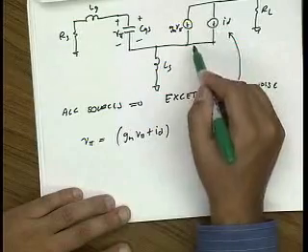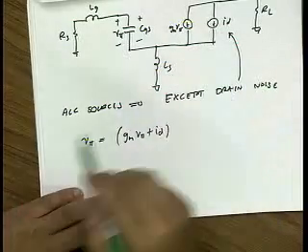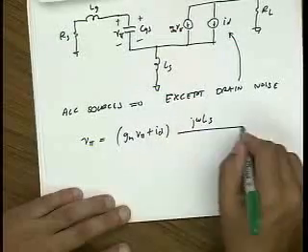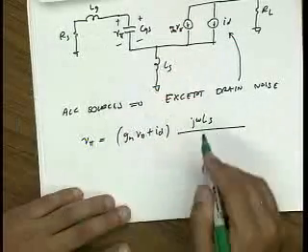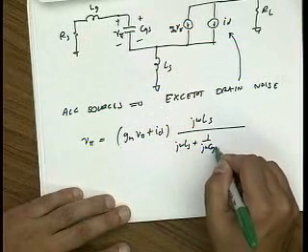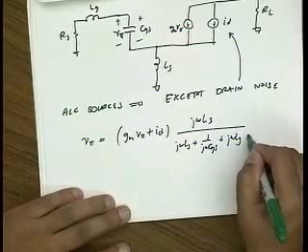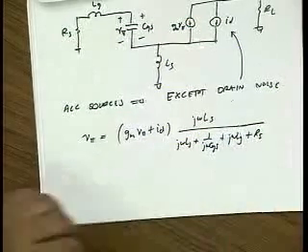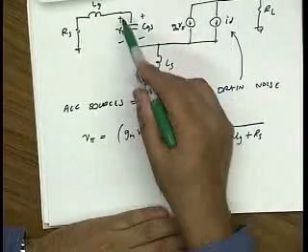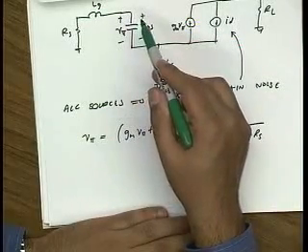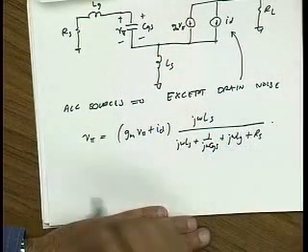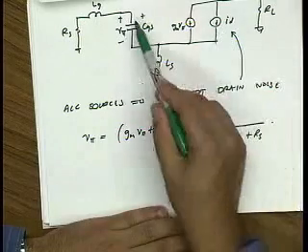These are the two currents flowing in, and then I have a current divider. So the current going in this branch is the impedance of this branch, j omega ls, divided by the sum of the impedances in both branches, which is j omega ls plus 1 over j omega cgs plus j omega lg plus rs. Okay? And this is basically the current that goes in times basically, let me make sure I got this right. So this is the current that goes here.